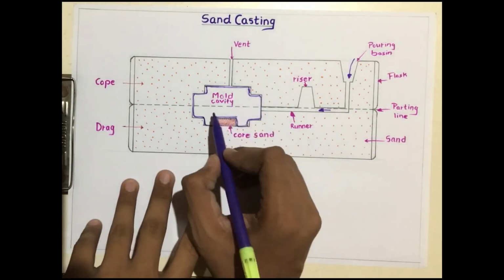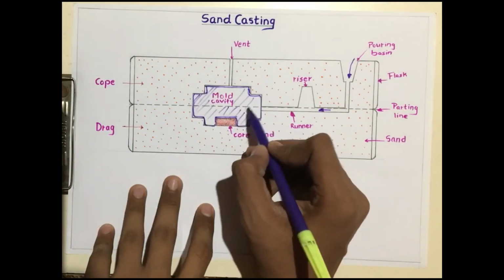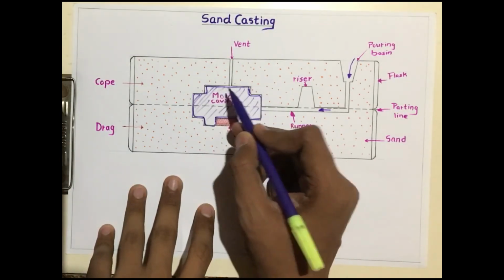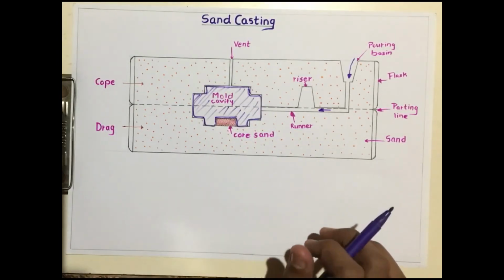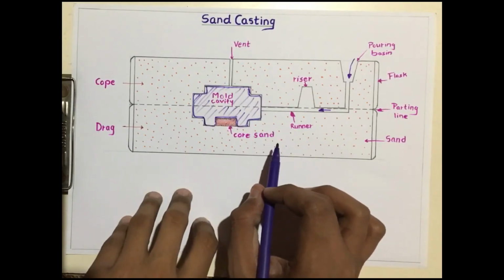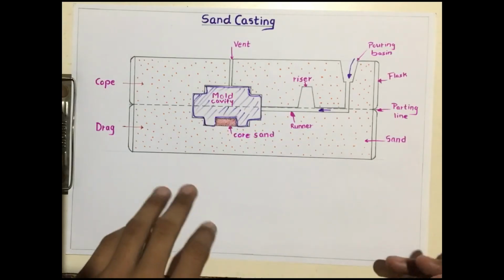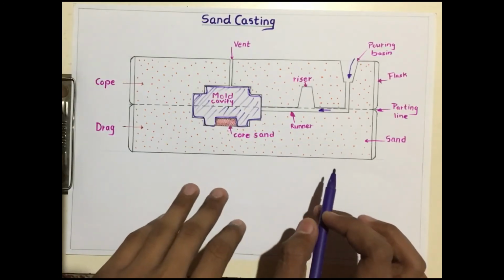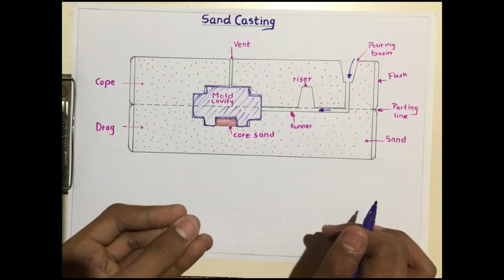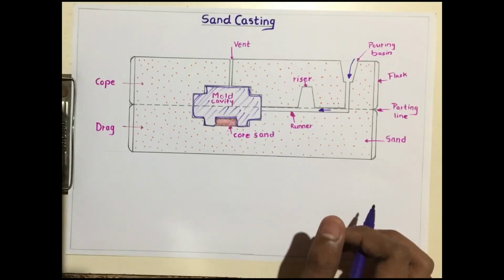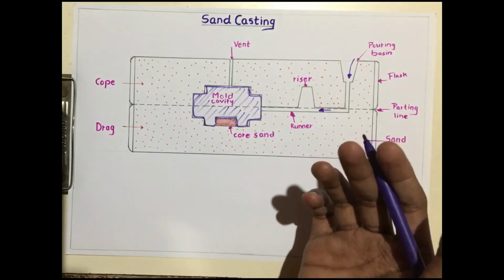After the solidification of the molten metal we should take the object out of this. Then we should inspect the object and if necessary we should perform some machining operations on it, because the surface finish in the casting process is very poor due to the sand crystals around it.